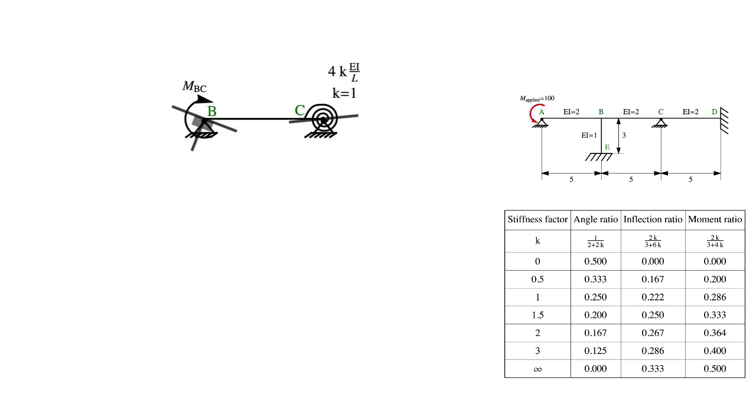We draw the stubs. The one at B should be there already, and the stub at C should have a slope equal to 1/4. We don't have to be so precise, we just draw a slope that is less than half of the slope at B. Now we sketch the deformed shape of this member and mark the approximate location of the inflection point.